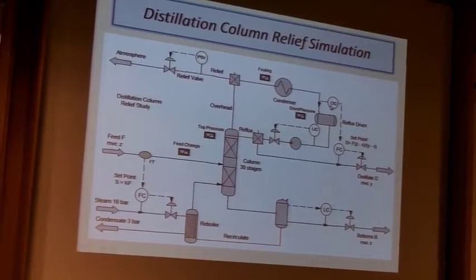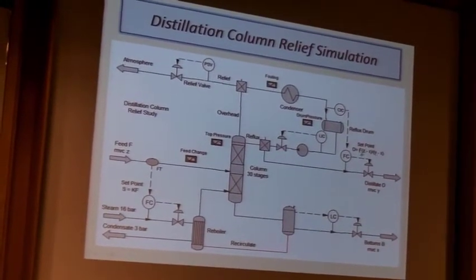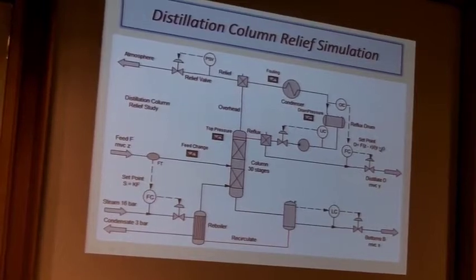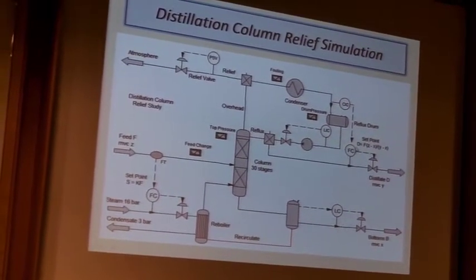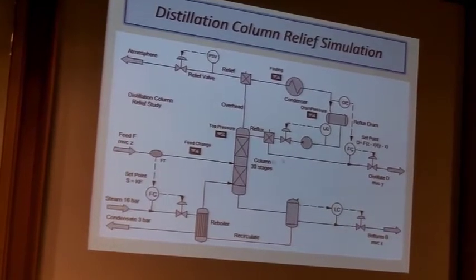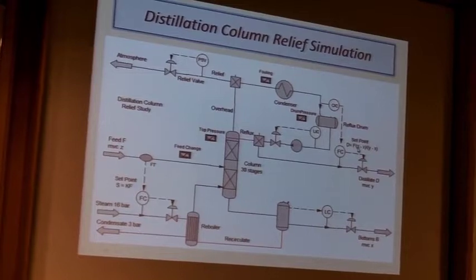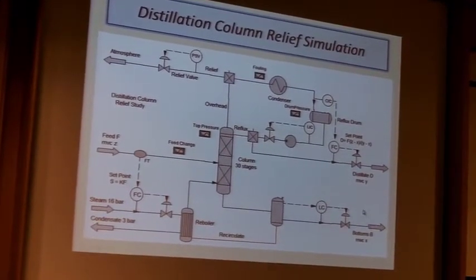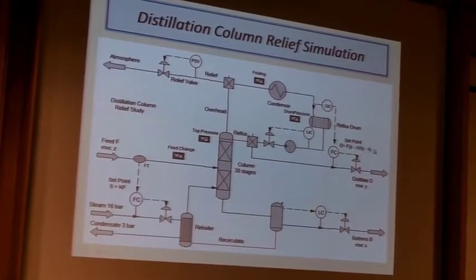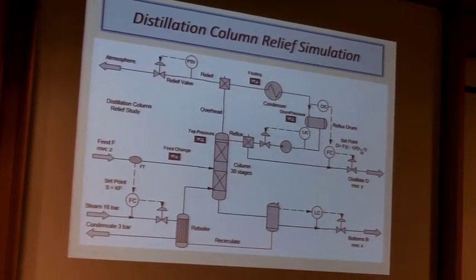I'm monitoring the composition here, and I'm actually taking a thing out of Shinsky's book just to mention him. I'm adjusting the distillate set point based on the feed flow and the composition of the feed, composition of the bottom, and the composition of the top. I've written that up a little bit in there, so just to give you background.